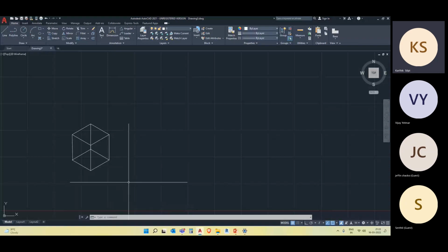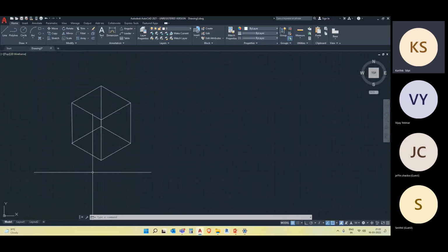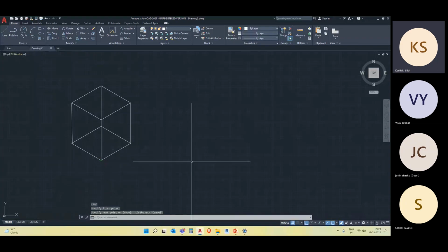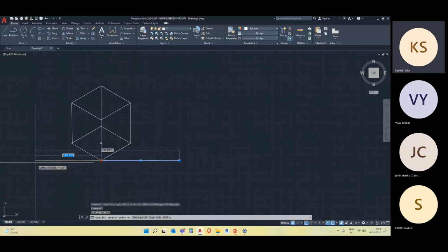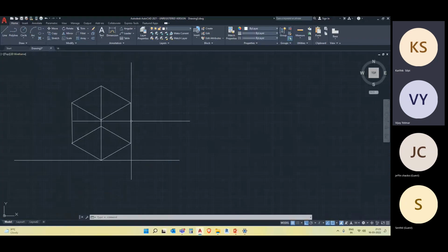You have to just get a hold of it, how to draw, and with baby steps, you can increase your pace. So with normal line commands or polyline commands in the actual drafting environment also, you can draw by giving just the angle. Now we have tried to give 30-degree angles, right? Let me just take a line like this. We have given 30 degrees angle to the straight line, and again here we have drawn a 150 angle in order to create this.